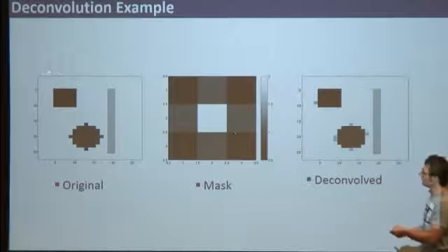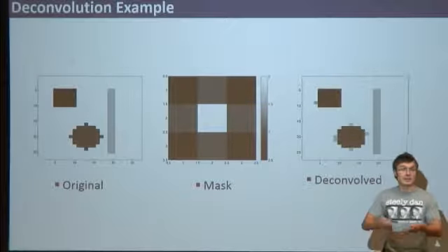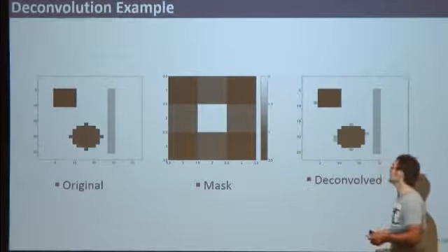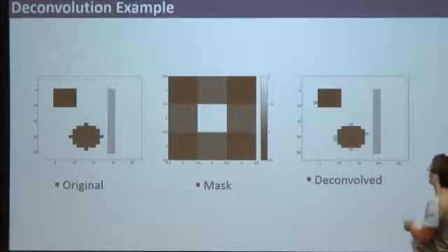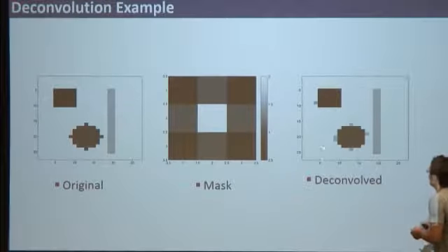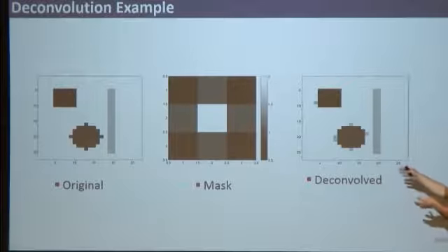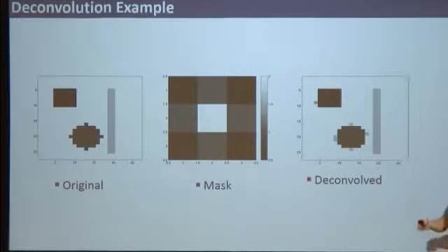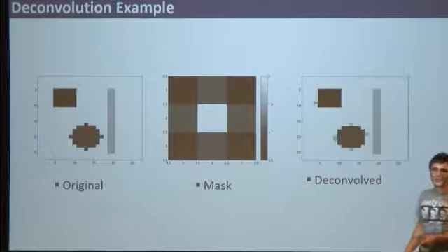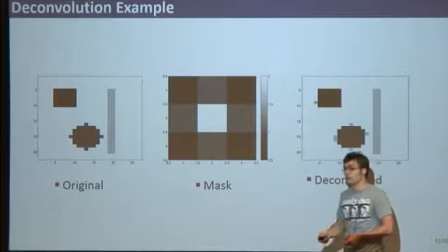So I convolve this with this mask, and I generate temporal signals using some pulse that I generated, and I add a lot of noise. Then I run the algorithm, and this is what you get. So you can get a reconstruction like this one even with 10 dB SNRs, so with a lot of noise, much more than you would get in practice from ultrasonic images. This is just to show you that this really works. It works surprisingly well, but unfortunately it's slow, and for real problem sizes it's still too slow for anything real time.